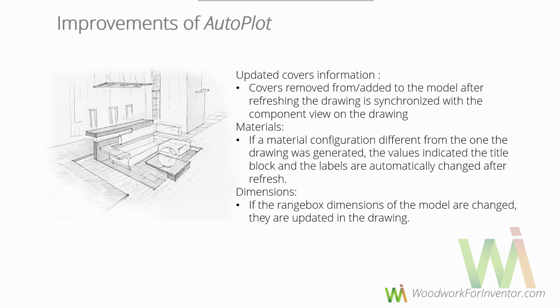And the last but not least is the dimension. As you know, the Autoplot tool allows you to export the range box dimensions. Don't make a mistake, this is not the dimension that you place on the drawing, it is the range box dimension generated automatically. So those also check if there are changes in the model at the moment that you update the drawing. And if the system sees the changes in the model, it automatically updates the values on your drawings.